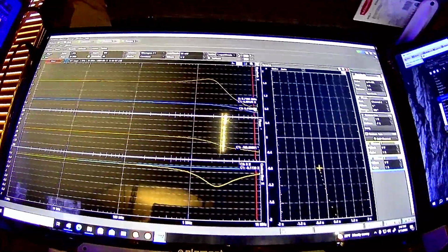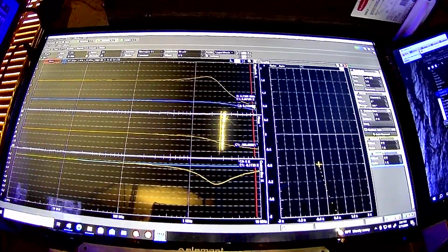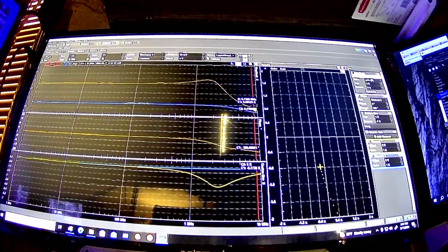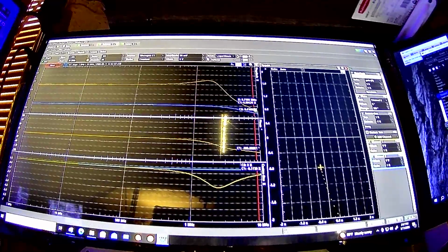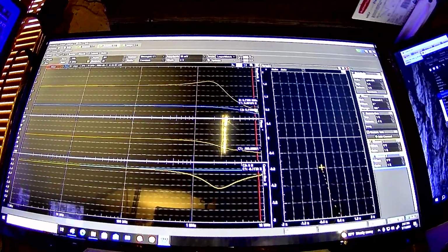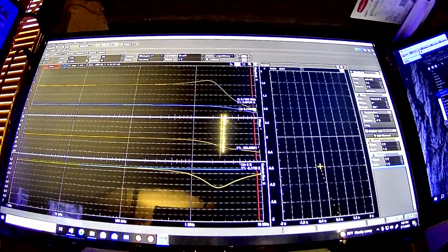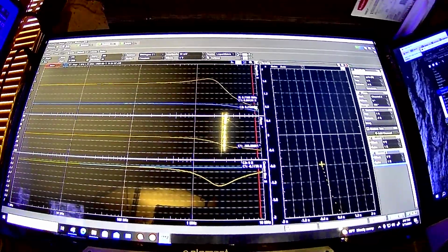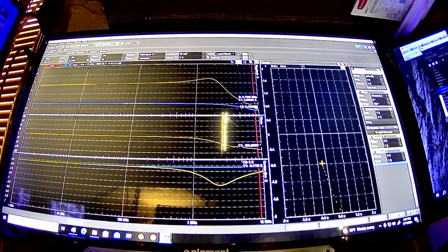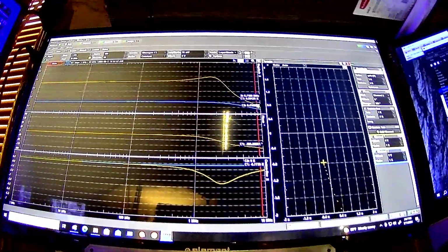No matter what happens, that's one of the reasons why sometimes they'll try to filter out high frequency noise on an op amp with a capacitor across its feedback resistor, but that won't always work with a non-inverting op amp because its gain can't drop below 1.